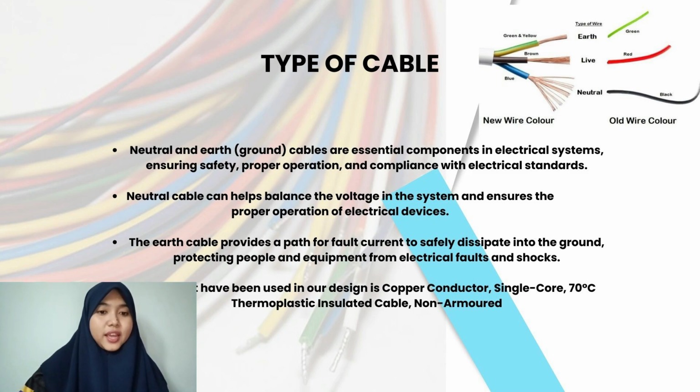So, the cable that has been used in our design is copper conductor, single core, 70 Celsius, thermoplastic insulated cable, non-armoured. So we have chosen this for our assignment.